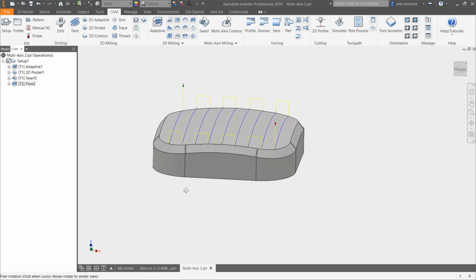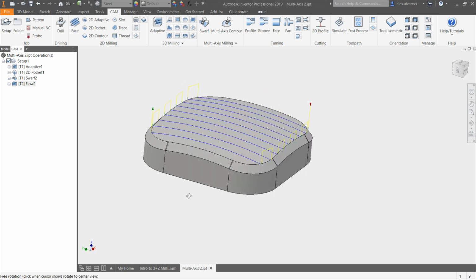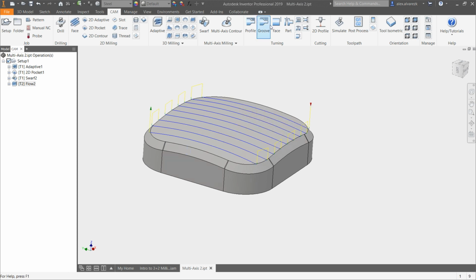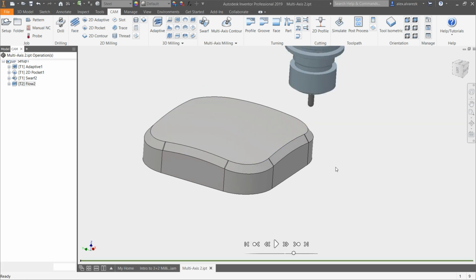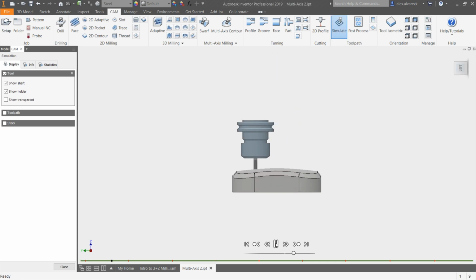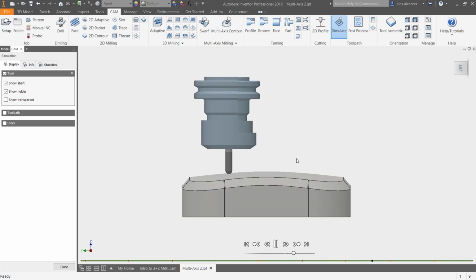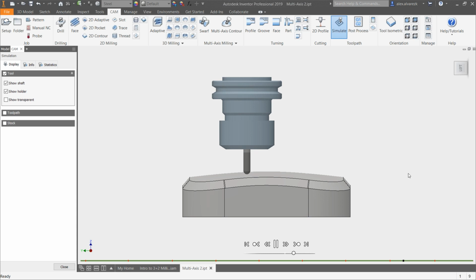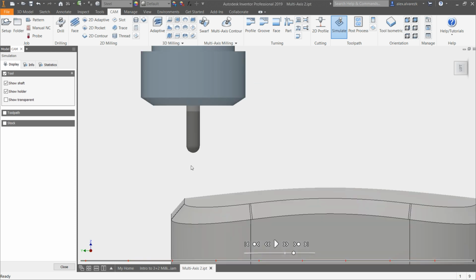And we have the flow toolpath here, right? So again, it has a pretty wide step over, so I probably wouldn't use this. But again, let's go ahead and simulate just so you guys can see how the tool is acting, right? Notice that it's acting more like a parallel toolpath. In this case, it's just going straight across the part. It's machining with the bottom, or the center of the ball end mill, which is probably going to leave us a pretty poor surface finish here.